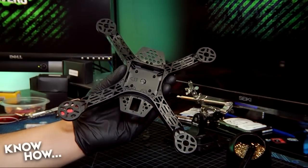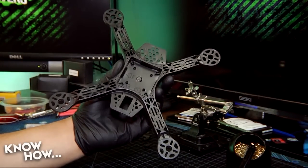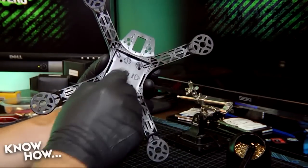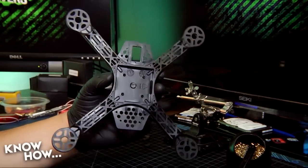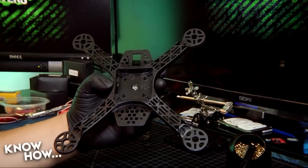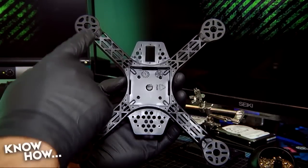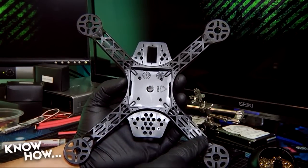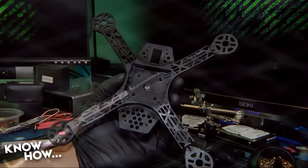With the soldering and insulation complete, it's time to mount the motors on the frame. We're using a Diatone 250 glass fiber frame with an extension kit. Orient the frame so that the cutout shelf is forward, then make a note of the arm numbering. Front left is number 1, front right is number 2, rear right is number 3, rear left is number 4.